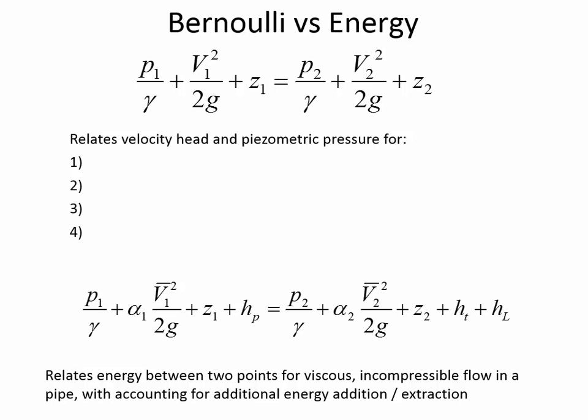The pressure head term is the same. Each term in the energy equation is going to have what units? Meters. Why meters? Well, we know that Z has meters, right? If we're going to add these together, then every term has to have meters. So that's the easiest way to know that it's meters, is that elevation is meters. But then if you look at all the rest of these, it works out to meters as well.